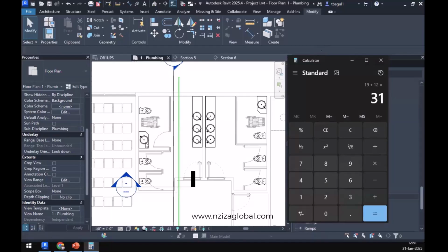Next. Now we have one water closet, and let's say we are connecting all of these together and we are connecting it over here. So one water closet comes over here. So now 31 plus only 6 from this side, but lavatory is 1, correct? So that will be another 1 coming up, making it 38. All right. Now this one is also coming in, which makes it a plus 6. We are at 44. Before you pick up this water closet pipe over here, your pipe size should increase to a 4 inch.